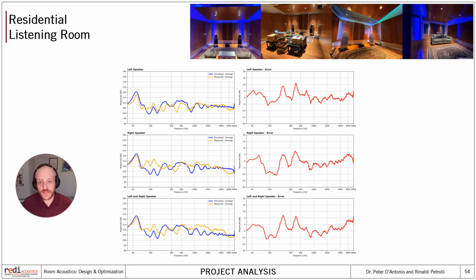We are comparing the measurements using our combined low frequency and mid to high frequency simulations. And here the discrepancy around 120 Hz becomes more apparent, where the left speaker seems to align better with the measurements, while the right speaker shows a larger deviation. It's important to note here that we are using 1/24 octave smoothing for this case, which will give us a cleaner view of the frequency response across the frequency spectrum. And despite the differences around specific frequencies, the general trend of the response is well captured.